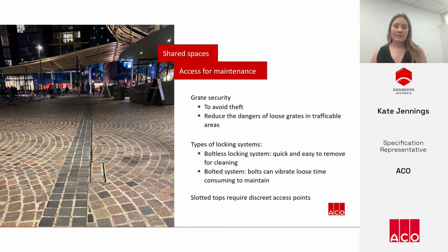The last element to consider is security, both to avoid theft and to reduce the risk of loose grates in trafficable areas. Using a boltless locking system on grates is a fantastic way to secure the grate into the channel, but it also allows for quick access for cleaning.